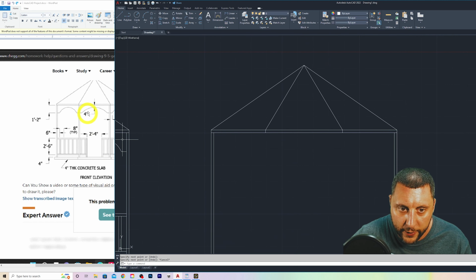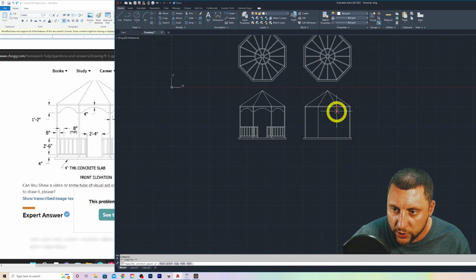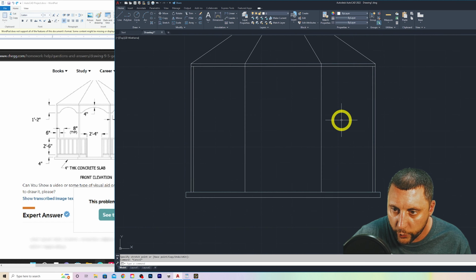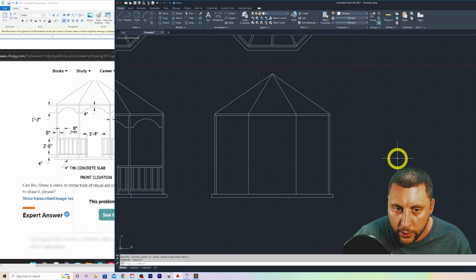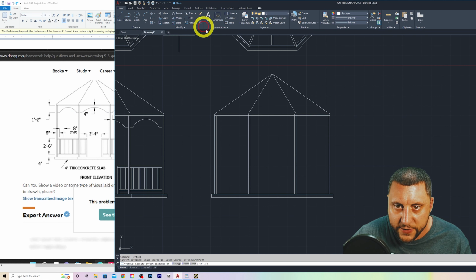Now, the 2x4 that's there, you've got a line and it goes down. That continues down. So actually, maybe I should have trimmed that before. I don't know. I didn't really think a step ahead there. But this one is now you're just going to pull that down. You can use the extend tool, or you can just click on it and pull the node down. And then you're going to do a 2-inch offset in and 2-inch offset in. And you can see that because it goes to left, to right. Okay. All right, next thing, offset 4 off the bottom line down.